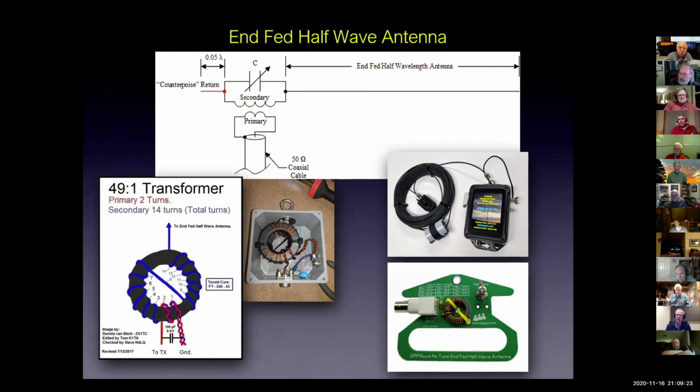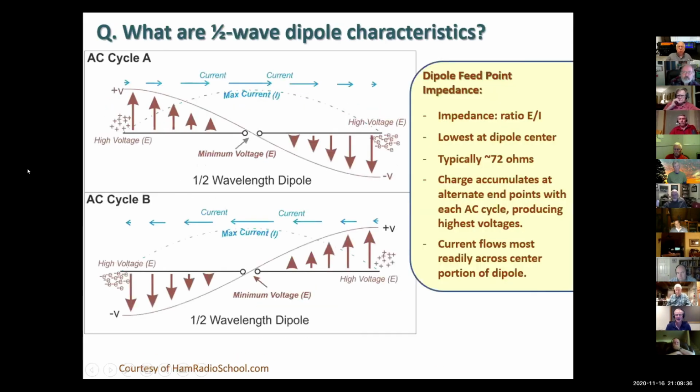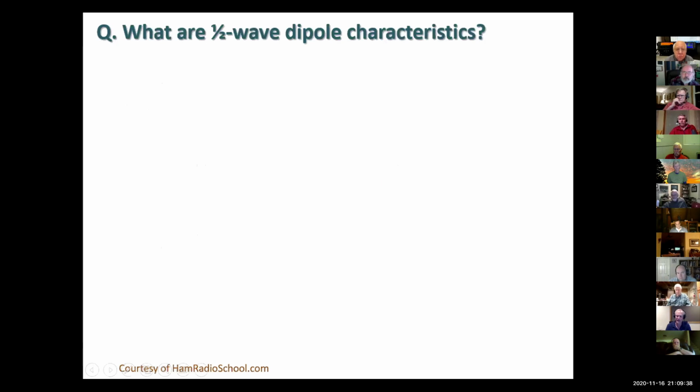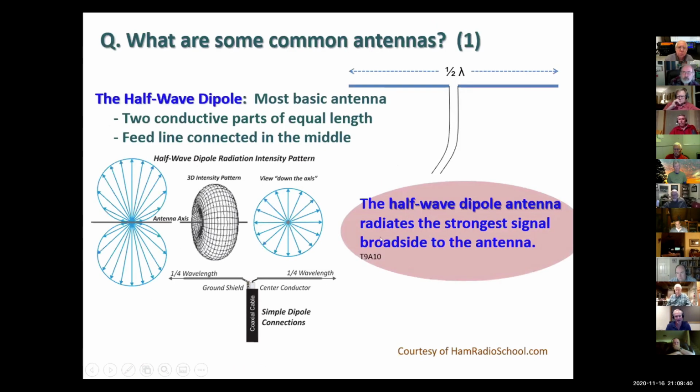Now, the one antenna we didn't talk about that's really in the dipole arena is something I think they call a doublet. Bob probably knows more about it than I ever will. But the idea is that instead of feeding with coax, you feed it with ladder line. The benefit, as I understand it, is that you still need to match so that you make your rig happy on transmission, so it doesn't fold back the power.